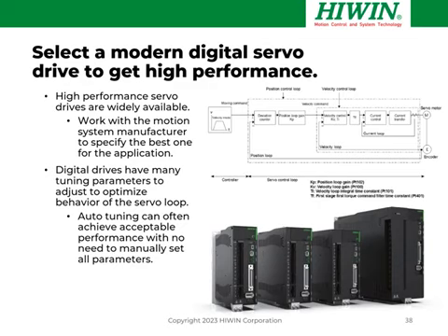power for the application. One thing that's really important to consider is that most modern drives are used in fieldbus architectures. So you may have heard of these, the EtherCAT, which is very popular because it's interoperable. Lots of devices run on an EtherCAT. Others include Profibus, Modbus, CAN bus, Ethernet IP. So if you're going to use a fieldbus architecture, of course, you need to ensure that the drives that you're using have the appropriate interface for that fieldbus.